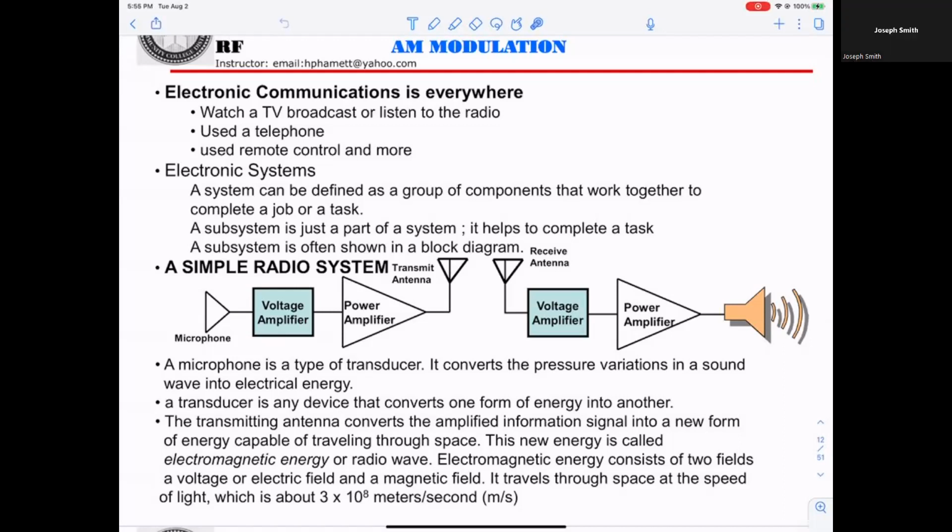Oh, 10 to 20? Yeah. And that signal cannot be transmitted over the air. Why? You need a really long antenna for that. That means the wavelength is too long. It occupies most of the space. So that's why it cannot.